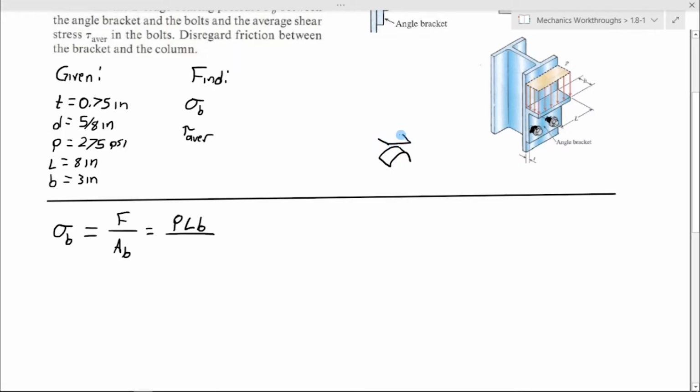And so that turns into a little rectangle. It is basically the area of that half cylinder looking from above. So the force is coming from above, and we find the area that is perpendicular to that. So basically looking down at the bolt, finding the area that you would see.